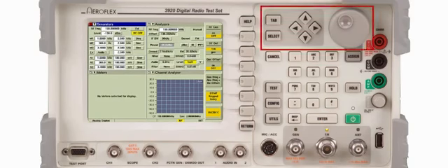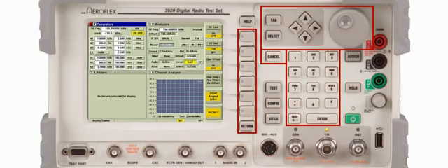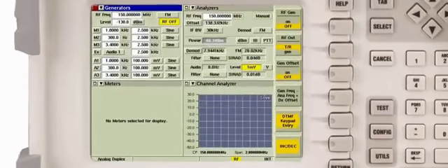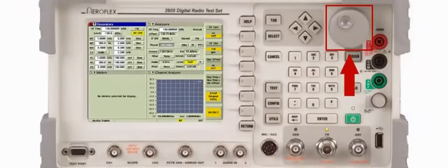illuminate. The 3920 front panel controls allow selection of data fields and tiles, entry of data, soft keys, access to configuration, utilities, and test screens, and access to specialized functions. The cursor arrow keys can be used to move between different fields on the display. The rotary encoder can also be used to select between fields.